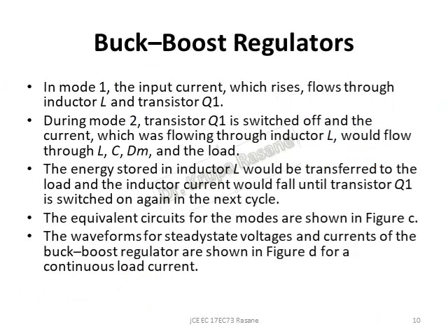Let us see how they work. In mode 1, the input current will rise and flow through the input supply, inductor L and transistor Q1 because it is turned on. In mode 2, the transistor is off and the current which flows through the inductor L would flow through L, C, DM and also the load.